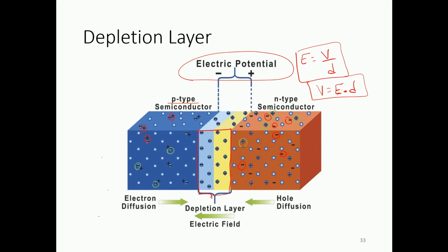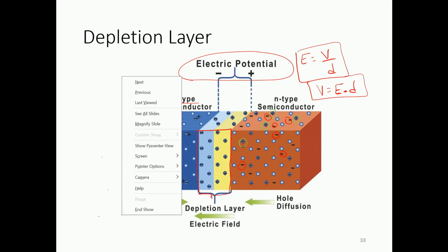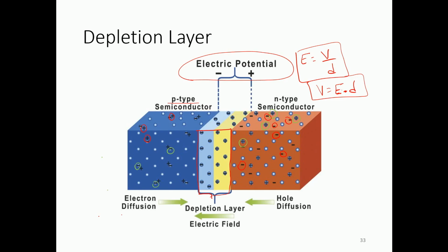Okay, so the idea is that whenever the p-type and n-type materials are brought together, diffusion of the majority carriers should happen left and right. The holes should move to the other side and the electrons should move to the opposite side, just to attract each other. Now let us look further at the atomic level and see how this biasing is happening.